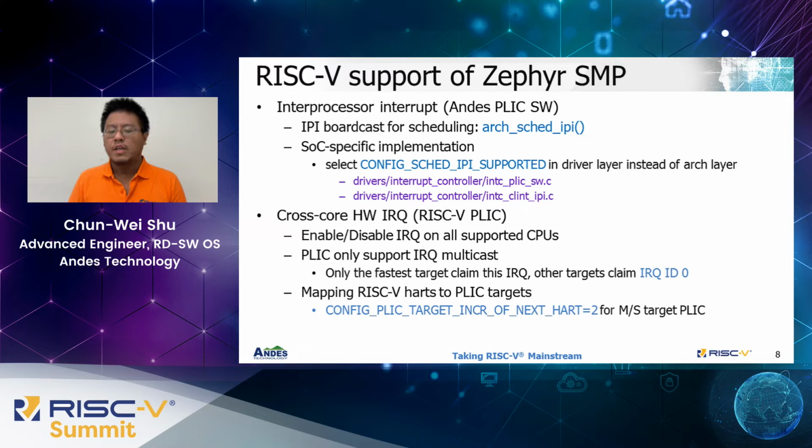To support IPI in Zephyr, the architecture will implement the IPI broadcasting API. Because the RISC-V IPI implementation is SoC specific, we will implement it and select the Kconfig symbol of IPI as a driver layer instead of the architecture layer.